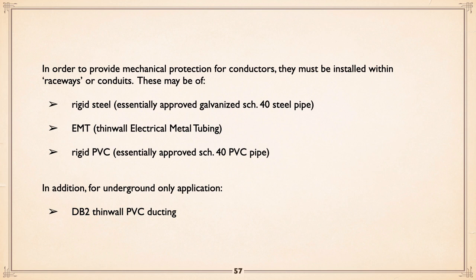Rigid steel is good in a situation like a pump station below a certain height, roughly standing height, where if a motor swings against it, you've got some reason. EMT is thin. Use it in a case where it's unlikely to get hit. EMT cannot be used below ground.